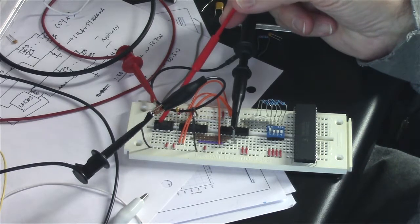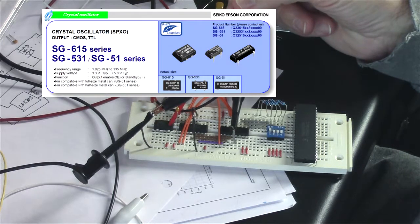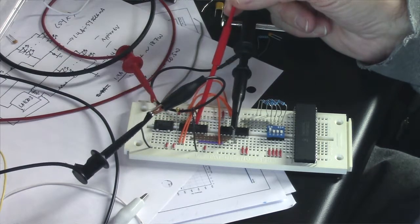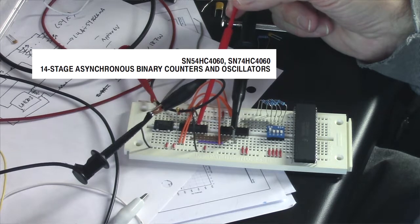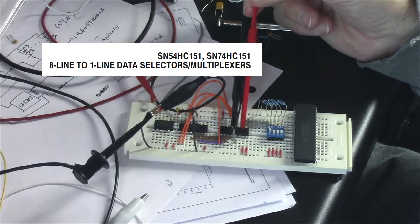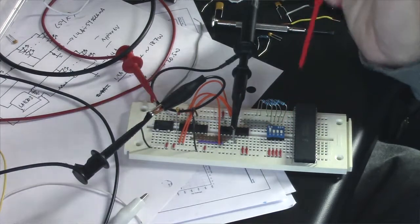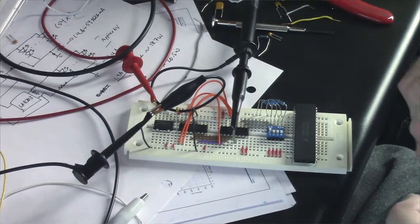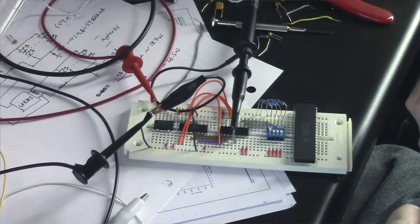This is an oscillator in a dip package. This is a 74HC4060 and a 74HC151, some dip switches. The data rates I need. Well, on the high end, for 38,400, I need 614,400 hertz. At the low end, 300, I need 16 times 300, or 4,800 hertz.